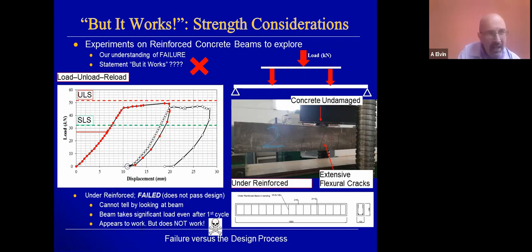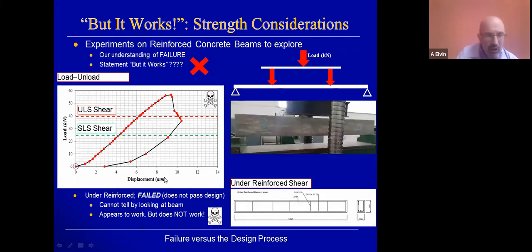That's what failure is. Failure is subtle. Failure cannot be seen by eye. But even under-reinforced, it has not collapsed. This still holds load. And if I were to put a third load cycle, it would still produce load carrying capacity. And now, just to complete this slide set, I will ask you about shear.